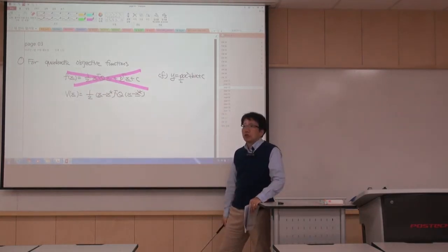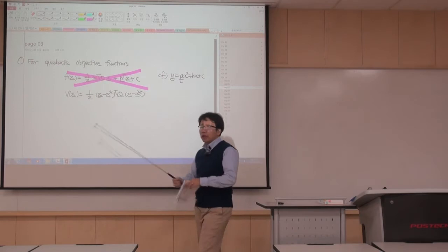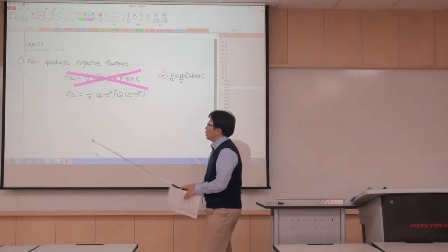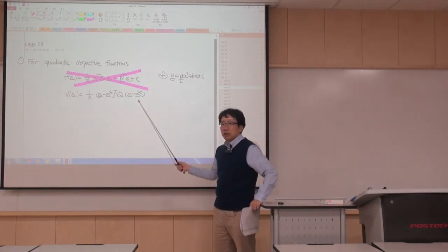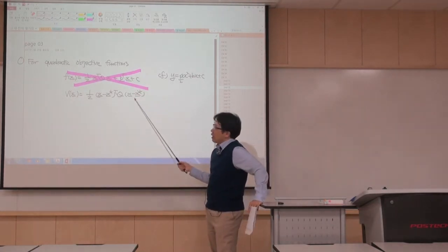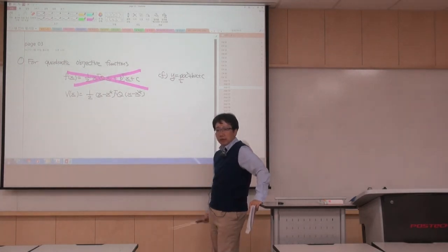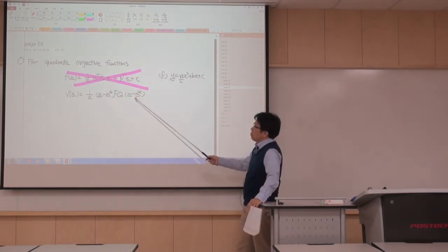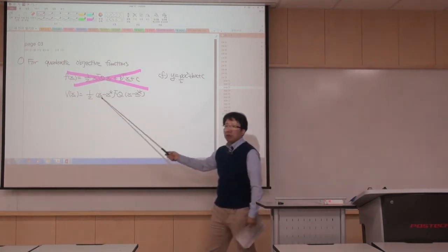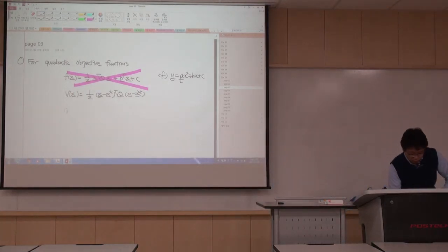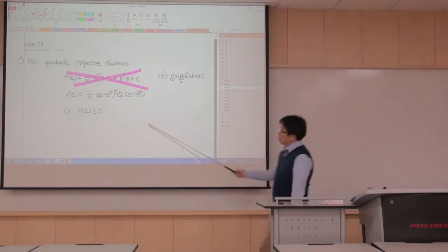Okay? So given any quadratic function, by adding a constant term, you can put it in this complete square form. And it does not lose any generality when we analyze the performance. The good property of using this V function instead of this general quadratic function is this. First, this V of x is always non-negative, right? Because it's a complete square.